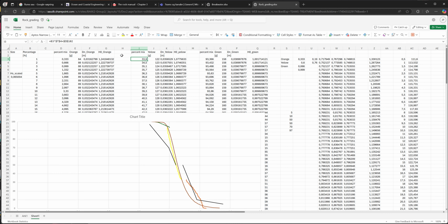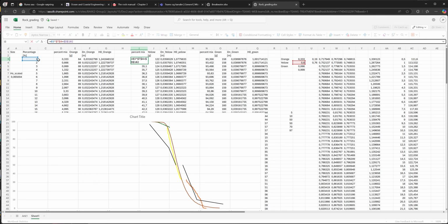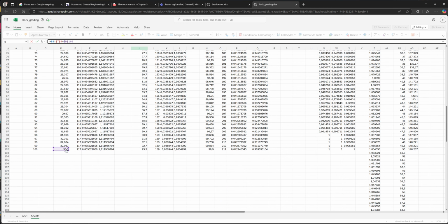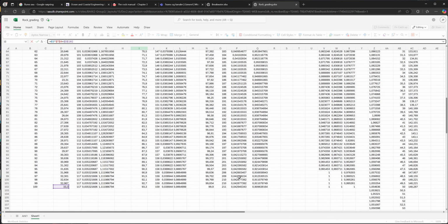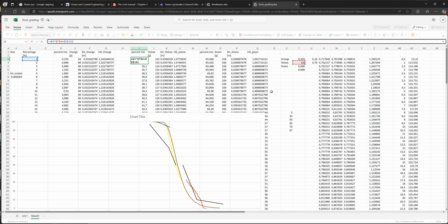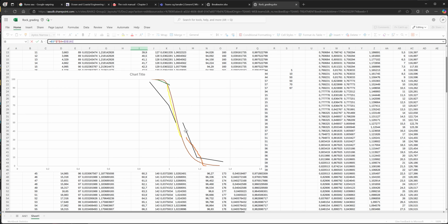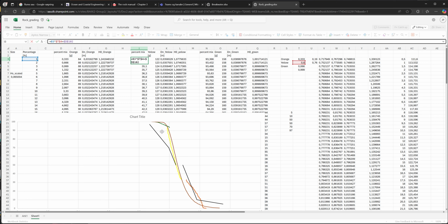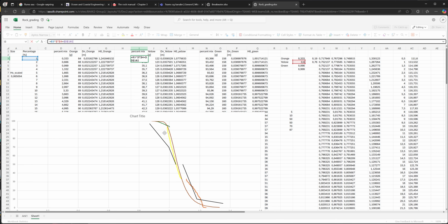And over here, we do exactly the same, like 1% times 0.6, so we add 0.6%, and then we add these 33.3%. And at last we should get 99.9, because I didn't use an overly large amount of decimals over here. So this is how the grading is done of the different stones for the armor layer in the flume.